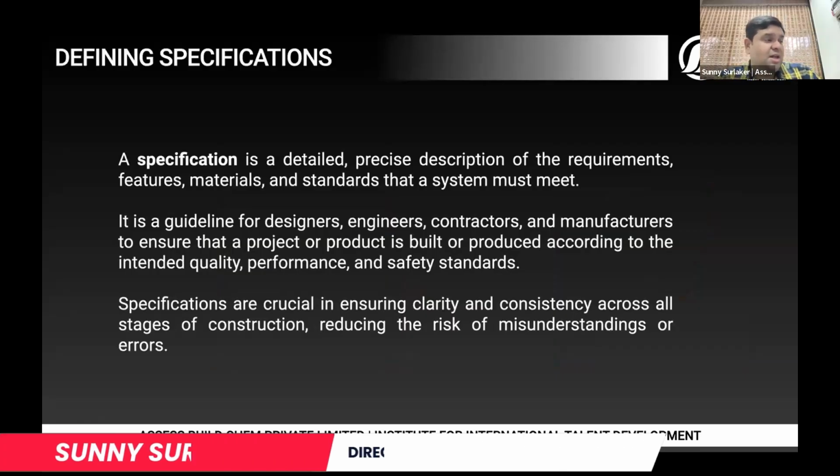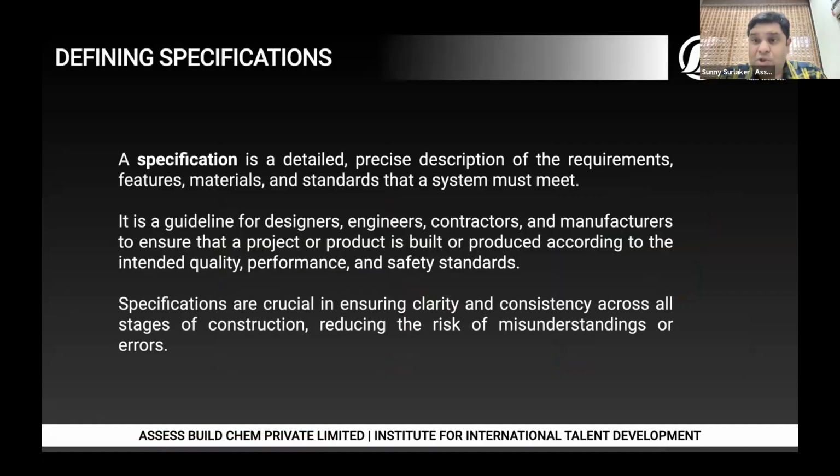Talk about specifications. Most people think that a specification looks like a BOQ, but that is not really so. A specification means simply that it is something specific. So it's a detailed description of whatever you're trying to do. So if you're talking about waterproofing, then there has to be a specific description of, say, how you take care of the surface. There has to be a specific description of what kind of materials you're going to use, how to apply it, and so on.